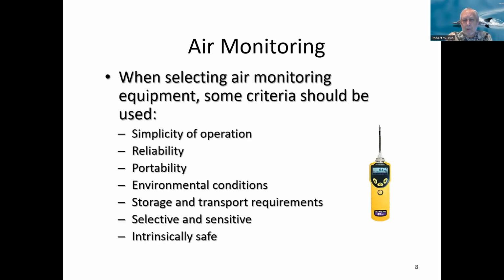When selecting air monitoring equipment, some criteria should be used. Good idea. Simplicity of operation. Yeah, I'm all in favor of that. Reliability, of course. Portability. It wouldn't be much good if it wasn't. Environmental conditions it'll be used in. Storage and transport requirements. Selective and sensitive. And is it intrinsically safe? Don't know how they determine that, but that's one of the criteria. It's a good idea to use.